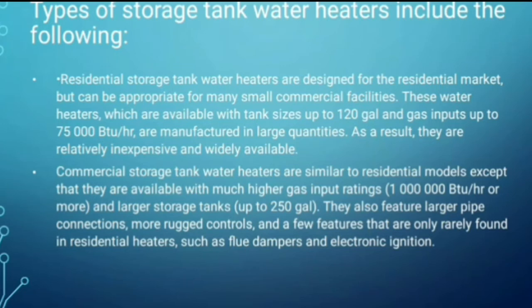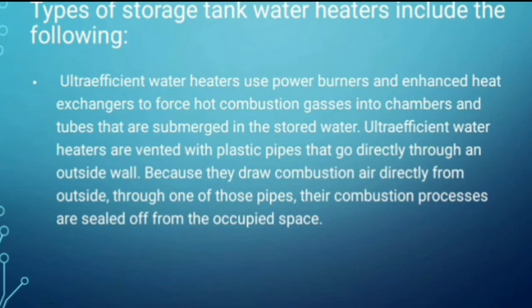Commercial storage tank water heaters are similar to residential models, except that they are available with much higher gas input ratings, 1 million BTU per hour or more, and larger storage tanks up to 250 gallons. They also feature larger pipe connections, more control, and a few features that are only rarely found in residential heaters, such as flue dampers and electronic ignition. Types of storage tank water heaters include the following.